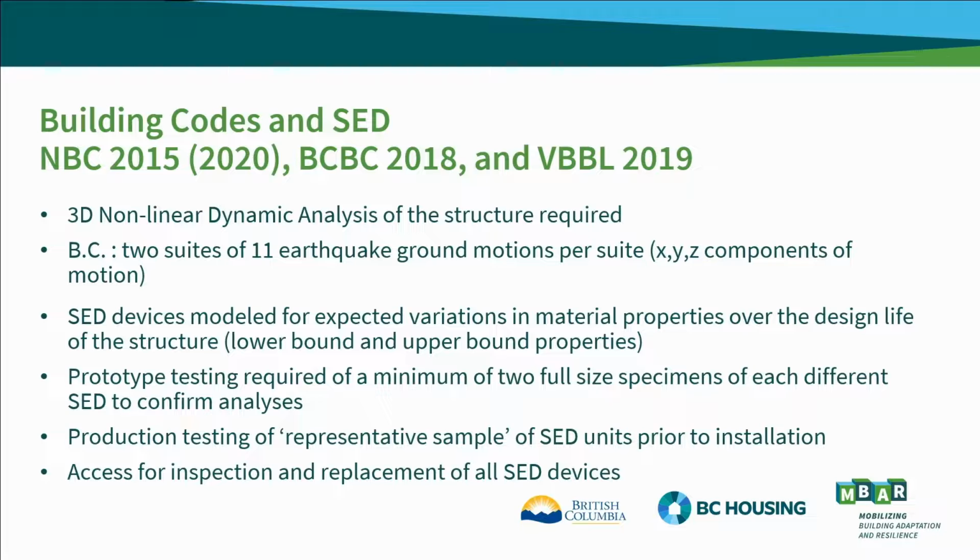The good thing about these devices, prototype testing is required for a minimum of 2 full-size specimens to make sure the real product reflects the analysis. And similarly, for the production testing, before the devices are sent to a site, a representative sample of these need to be tested to confirm that they're within the properties that have been designed and analyzed.